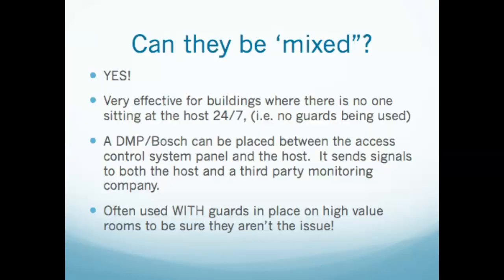But that would be way too easy because I like to mix them. And they can be mixed and they can be very effective when there's nobody sitting at the host 24/7. So you could have somebody sitting at the host all day when your building is really active and there's a fair amount of alarms coming in because people are tripping stuff and you forgot to turn something off or you don't have it zoned and there's alarms coming in. But then when everybody goes home, you set the DMP panel and you shut the host down. And then all those alarms are going to go to that central monitoring station where they'll take care of it for you.